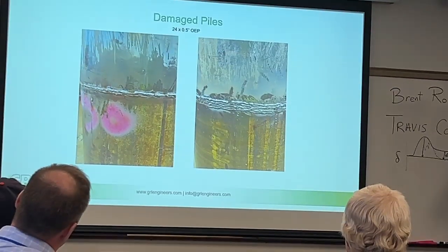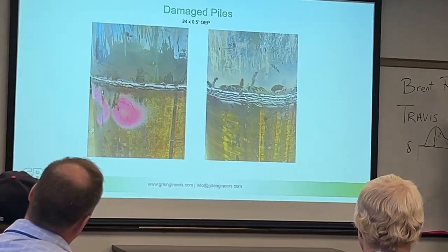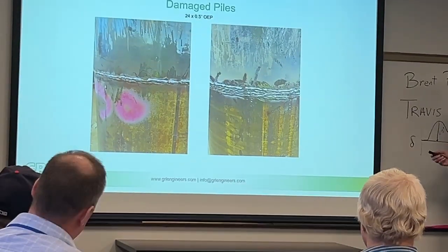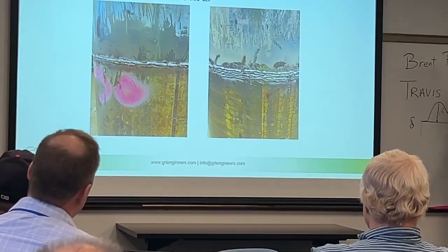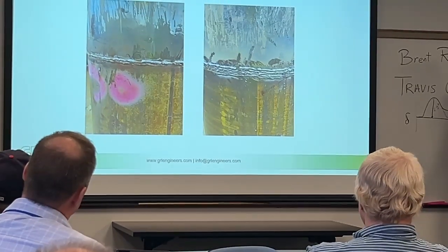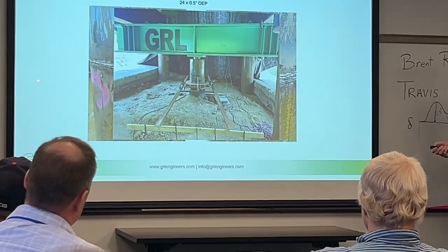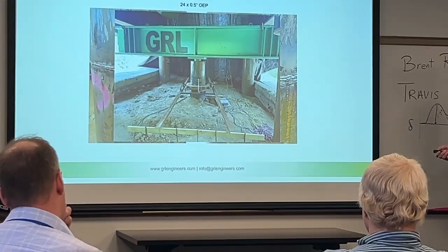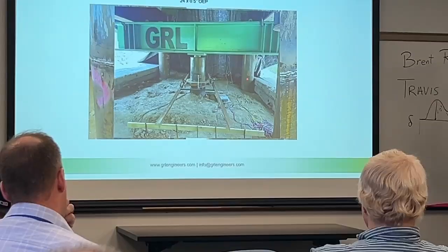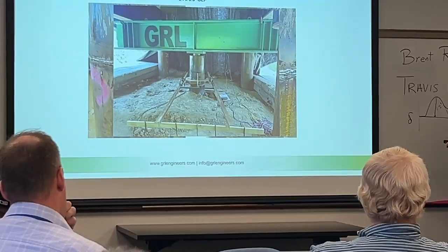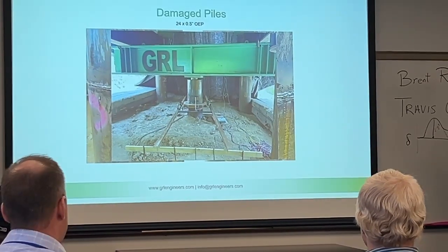The big concern with this splice, so this splice was damaged, we replaced it, but he had also spliced some of the reaction piles of the static load test. So now we're running the static load test, and 2 of these 4 piles have Mr. Suspect welder's splices not very far below the ground surface. So we're somewhat scared to run this static load test.